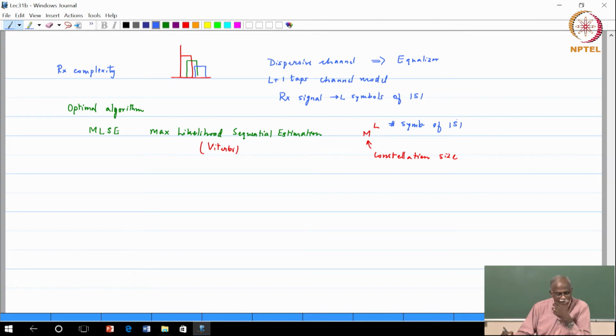Okay. So, here is a simple example and we stop with that. I have a 4G system, I have a bandwidth of approximately 10 megahertz, that is the bandwidth of my signal. Now, bandwidth is related to baud rate, the number of times you use the channel. It is related to bit rate also, but through the baud rate: baud rate times the number of bits per symbol is your bit rate. So, baud rate is a more fundamental quantity when you talk about the bandwidth. So, this is related to the symbol duration, right. 10 megahertz means I am sending approximately 10 million symbols in a second.